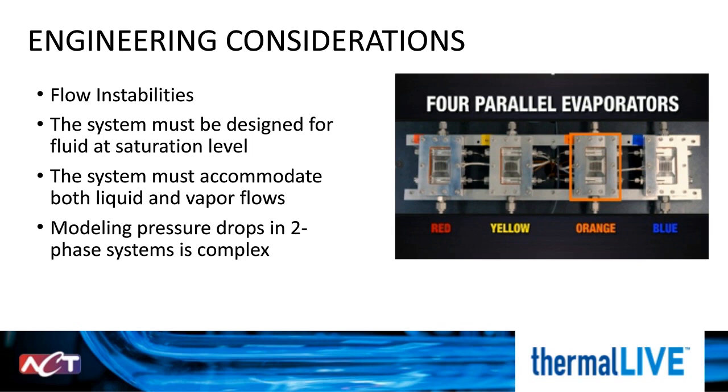A well-designed system will be able to work with multiple evaporators. However, the solution is not straightforward. The system must also accommodate both liquid and vapor flows. This means that understanding and knowing the vapor quality throughout the system is critical. And finally, there are very few programs that accurately model pressure drops in these two-phase systems. It is critical the designer has the ability to calculate and model this complex design.